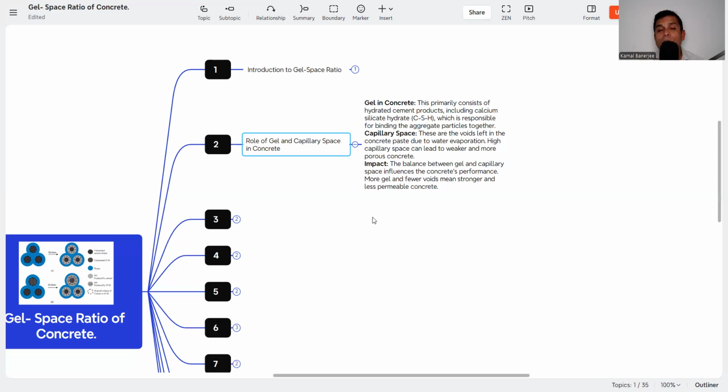If the concrete is weaker, that means we will not get that much strength. And if it is porous, what will happen? The water will penetrate inside the concrete, and carbon dioxide, chloride, sulphate and other harmful chemicals also penetrate inside the concrete. And if they penetrate, then water with the calcium and everything causes deterioration of the concrete and corrosion of the steel will occur. Again, it will deteriorate the RCC structure or the stability of the concrete. So that is why it is important.